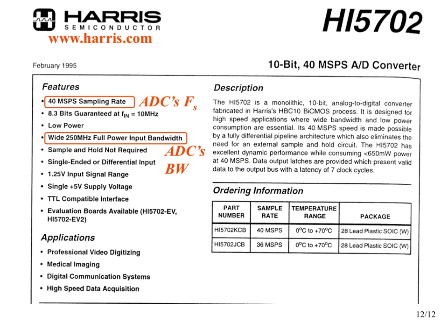And just one final slide. This is by no means an up-to-date A to D converter. This is probably from 15 years or so ago, and I'm sure they have much better ones now. But this gives you an idea, and you can see right away on the very first page they're advertising those two key characteristics: the sampling rate, which for this A to D converter has a maximum of 40 megasamples per second, and the A to D converter's bandwidth, which is 250 megahertz.